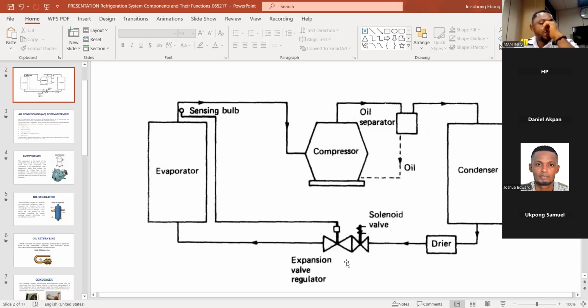Your question is related to a system that is using single phase, because in a three-phase compressor, you don't need a capacitor to run the compressor. But the indoor unit fan is always single phase, so you use a capacitor. For example, in a residential system, both the indoor and outdoor units are single phase. So what does that mean? In every single-phase induction motor, you need a starting capacitor. Your fan in the house is also using a capacitor.